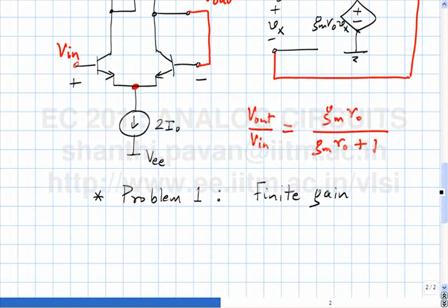So if you have two amplifiers of gain 100, you can put two of them together and if you cascade them, you'll get a gain of 10,000. You understand? So, we'll list out all the problems and then put together solutions to all these problems in one shot. There's one problem, which is finite gain, and we already seem to have an idea of what we need to do to fix it, which is cascade multiple stages and you'll be able to get more gain.